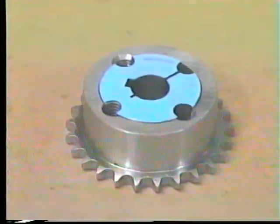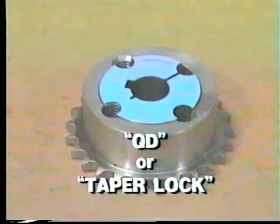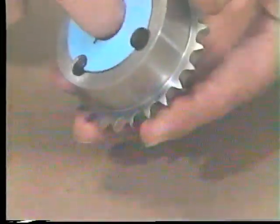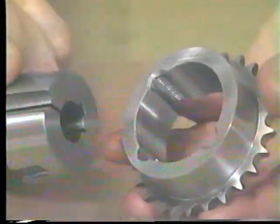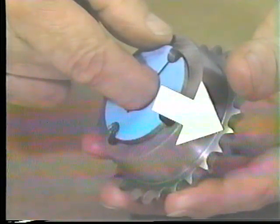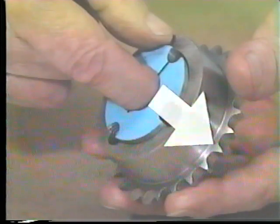Chain coupling sprockets are available with taper lock hubs and with QD or quick disconnect hubs. These special hubs clamp themselves to shafts of different sizes, so the bore of the sprocket does not have to fit the shaft precisely. Another type of chain coupling uses standard stock sprockets, like those for power transmission chain drives. These sprockets may be taper lock, QD, or they may have a standard stock bore.